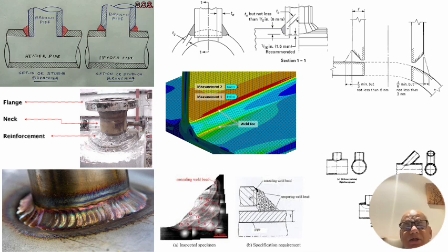So how to start and stop this number of passes and where to merge as you take a 360 rotation on the weld becomes important. And finally the stress values: if you see here, the measurement near the toe of this upper fillet, which is the last one to be welded, has gone up almost 30 to 33% higher, from 3000 units to 4000. So there is a jump of almost 1000 units in the stress level, and that's how it comes into play.